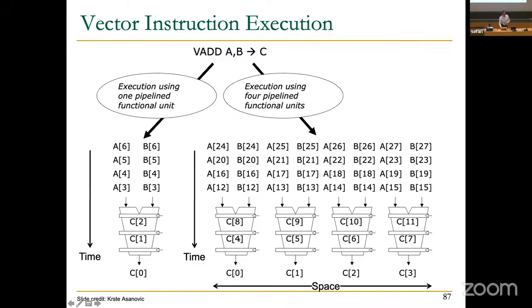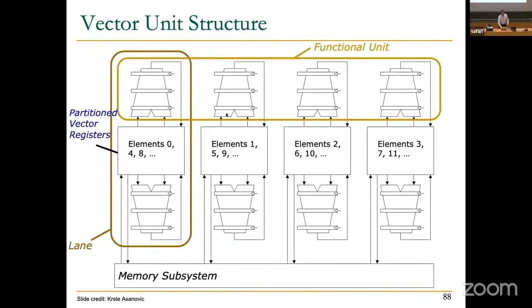That sounds good. Now you can also customize the register file. Elements that are numbered 0, 4, 8, 12, 16, 20, 24 go to this one. The other ones go here. Basically, there's a mapping, a partitioning of the register file across these functional units. Not all registers need to feed all functional units. This makes it a little harder to program later. So this is what a GPU kind of looks like today.